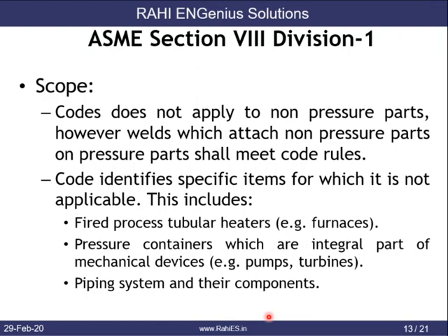Code does not apply to non-pressure parts. However, welds which attach non-pressure part to pressure part shall meet the code rules. It also identifies specific items for which it is not applicable. This includes fired process tubular heaters, pressure containers which are integral part of mechanical devices, piping systems and their components.